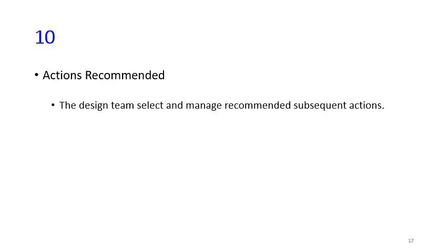Finally, in the last column, based on the RPN numbers, the design team should think about the actions recommended for each failure mode. Based on the risk priority number, the design team can see which failure mode should be prioritized because it has the highest risk.